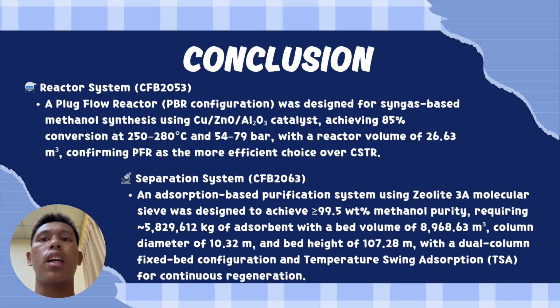It requires 5,829,612 kg of adsorbent with a bed volume of 8968.63 meter cube. A column diameter of 10.32 meter and a bed height of 107.28 meter with a dual column fixed bed configuration, and temperature swing adsorption TSA for continuous regeneration.